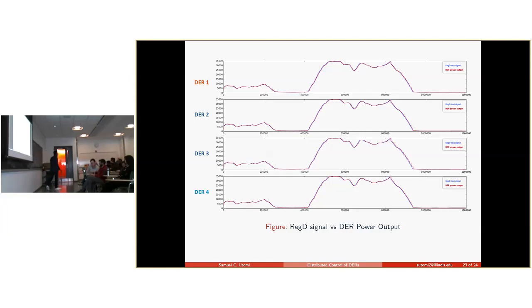Each DR is implemented in the HIL. It's a combination. We have a hardware controller on the outside, a physical controller, and then you have a local power controller that is modeled inside the Typhoon HIL simulator. So the DR has two components, one that is physically existing and one that is simulated. In the HIL part, it's a set of linear differential equations. What was the order of that equation? No, I'm saying it's not linear. It's a full-blown model of the system. So the switching transients are involved. Switching is even involved. Yeah.